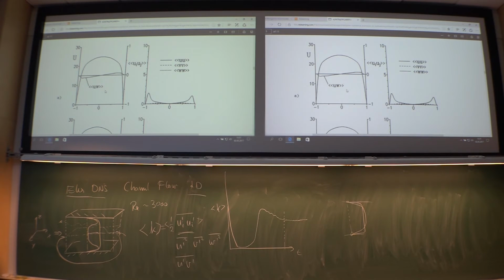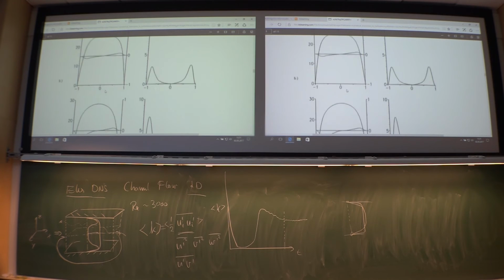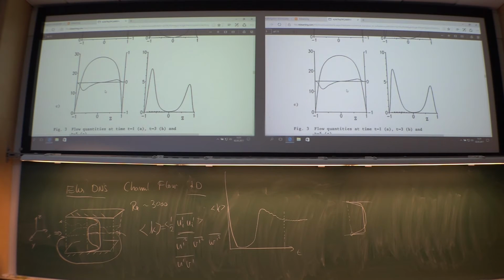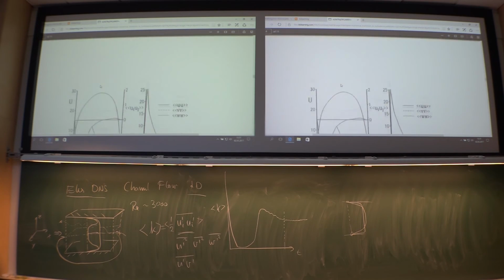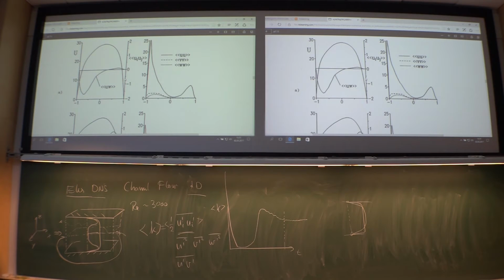But now look at the development. He tends towards the parabola, clearly. So closer and closer to the laminar solution, which I was not interested in. But luckily, he starts now developing real turbulent flow. But he started at the left wall first. And there also you see the shear stress now starts to build up.